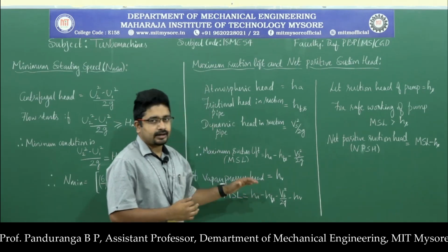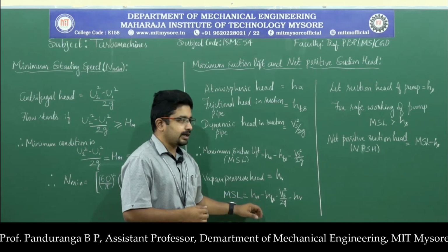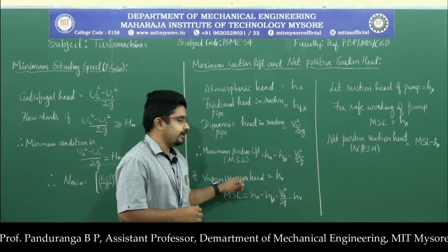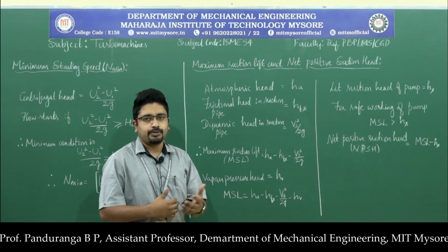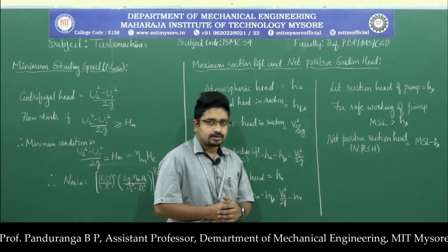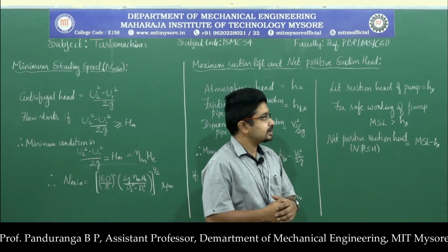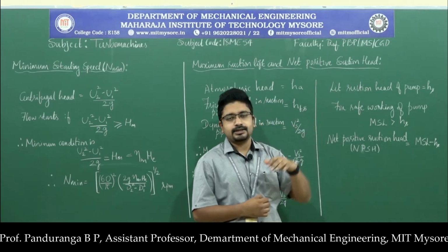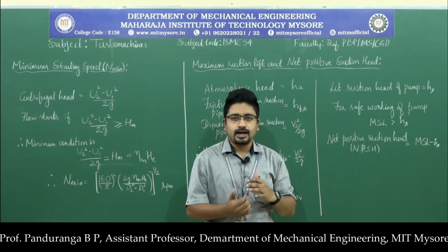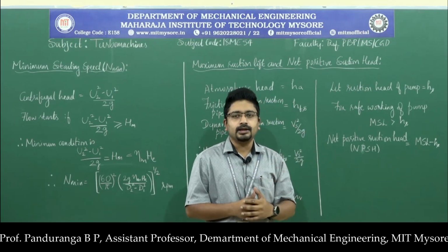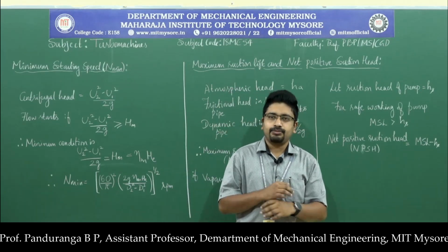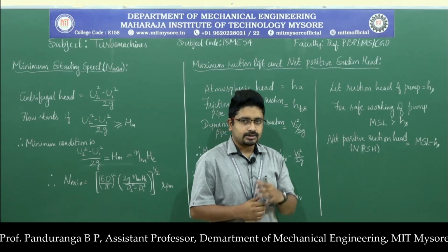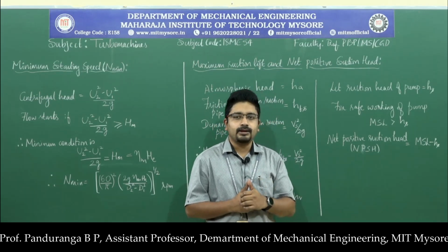Now, to guarantee that there is sufficient head available, so that no cavitation occurs and no formation of vapor occurs in the pump, we have a concept called net positive suction head. If the value is positive and higher, that guarantees there won't be any formation of vapor bubbles in the suction pipe. So that guarantees the safe working of the pump.